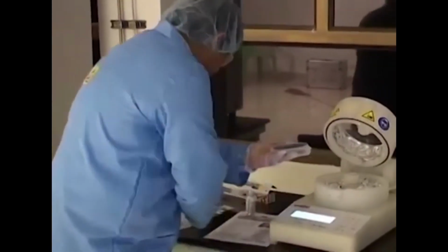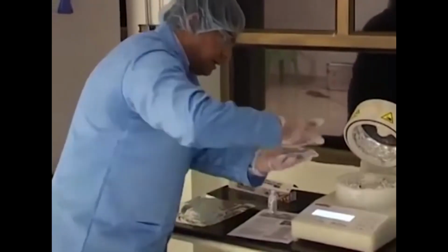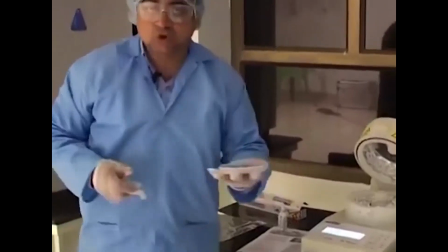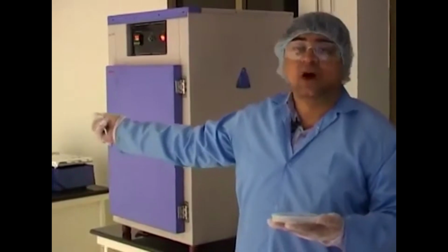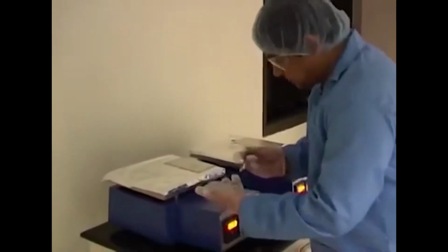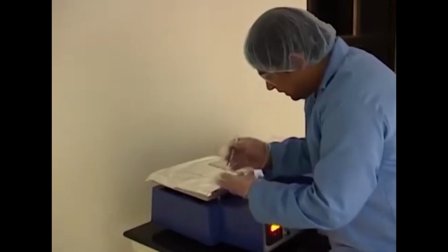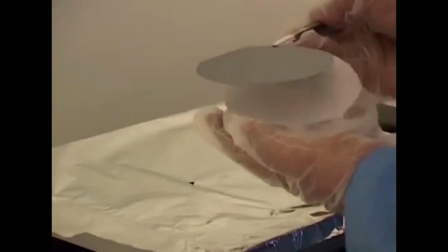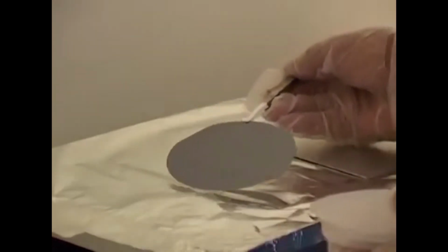And then once we have done it, we cover it with this cover here, not pressing it very tightly, and then slowly move towards our next step, which is the hot plate, and keep it on the 65-degree set hot plate and wait there for about 3 minutes or so. So I am going to put this wafer now on the top of this hot plate, which has been set at 65 degrees. For doing that, we have to be again very careful about pulling this resist coated wafer out. We use the exact same area as before for holding, just a small edge or a small corner, and then keep it on the hot plate.